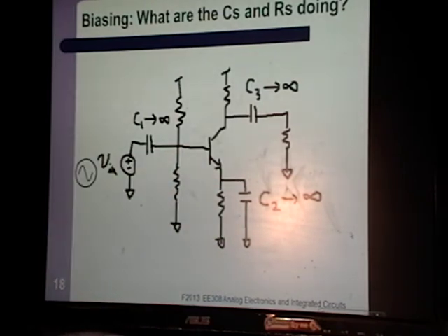I mentioned a couple times earlier in the quarter that when you run digital circuits, sequential circuits, every time the clock ticks, a bunch of electrons get thrown onto the supply, and a bunch of electrons get pulled off of ground. Electrons are negative, so if you pull a bunch of negative things off of ground, ground becomes more positive.